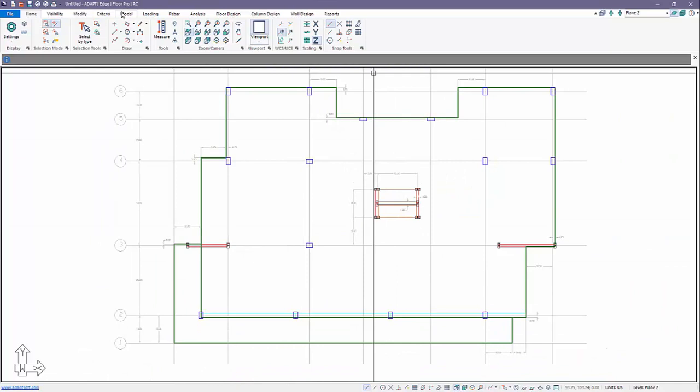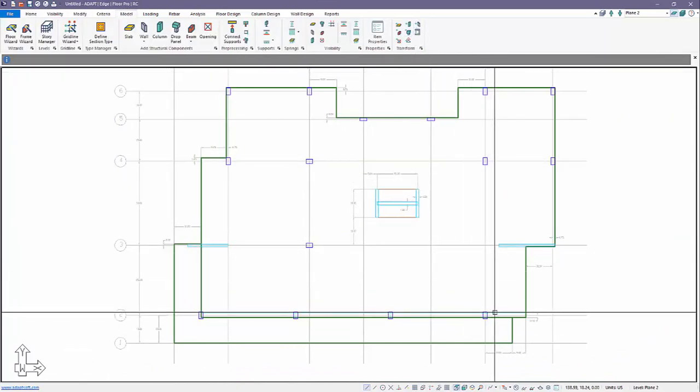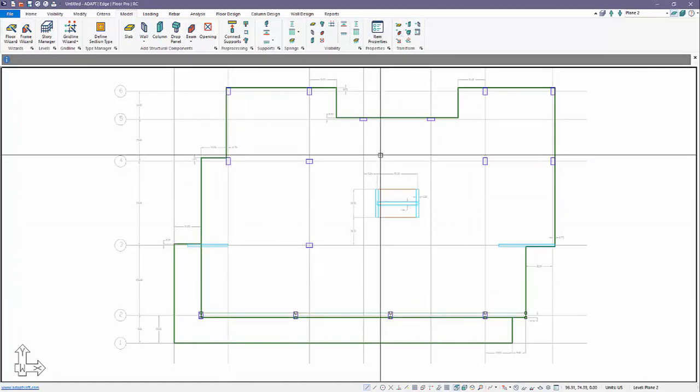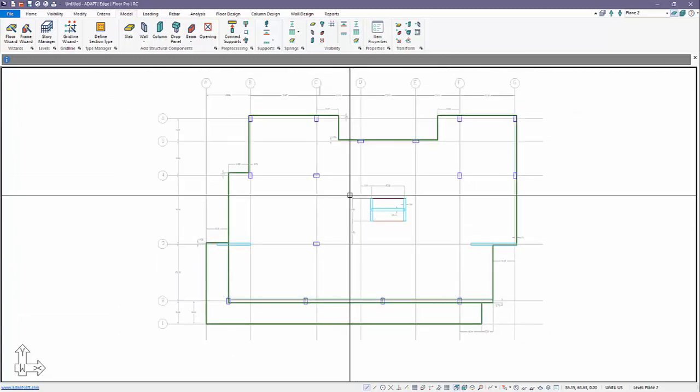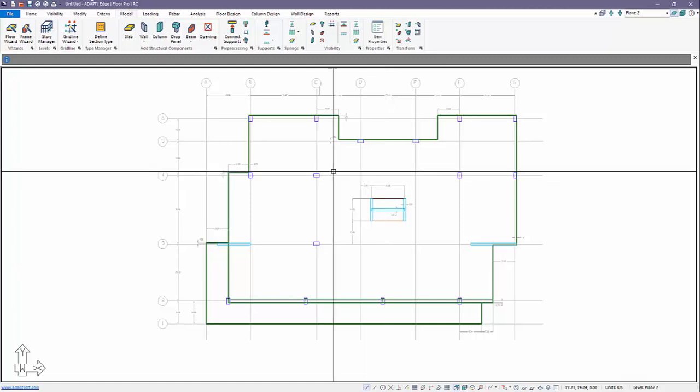Okay, so we'll go over here to model again. Those are transformed to walls, and the last thing I have are polygons representing my beams, and we'll transform those to beams. So now we're left with a structural model. I'll turn my CAD file off. I may not want all of those lines. If we want a separate grid file, we would have to import that separately.